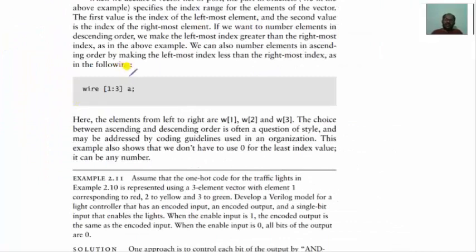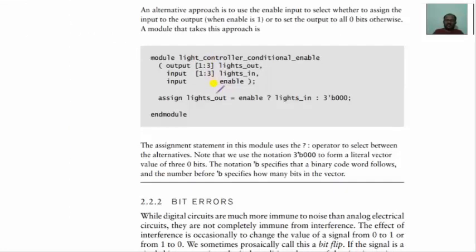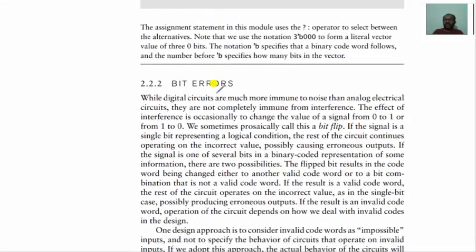All the intermediate results you are going to write as wire, but all the outputs, if you want to store for further processing, we are going to declare as registers. This is very, very important.